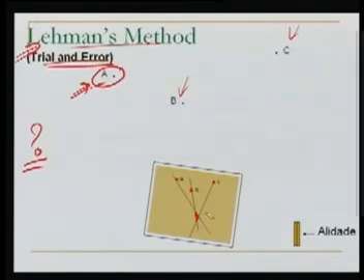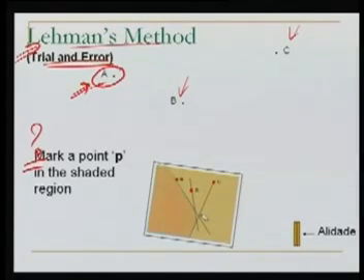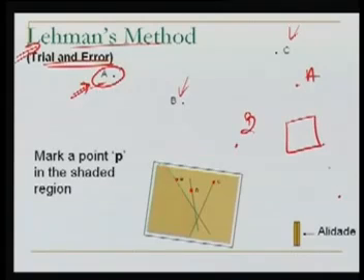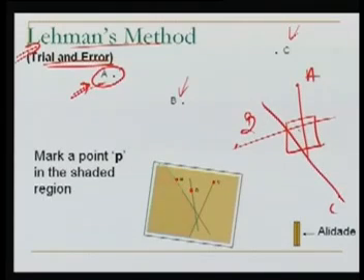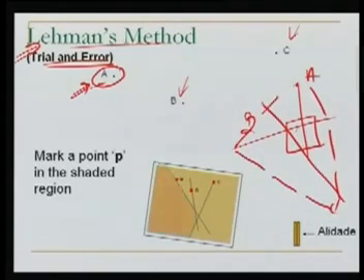How do we do that? Well, in order to reduce that, the next step is we locate an area where this point will be. Now, how will this area be located? It's very easy. Let's say these are the control points A, B and C, and our triangle is formed here like this. This is the triangle of error. It's very obvious, because we are inside the great triangle. We say this is the great triangle, which we are using for our resection. Our point P will also be inside the triangle of error.